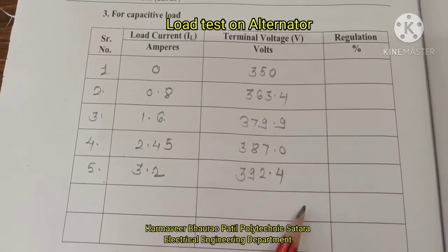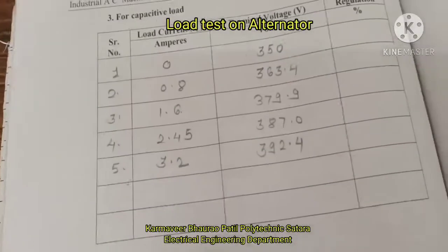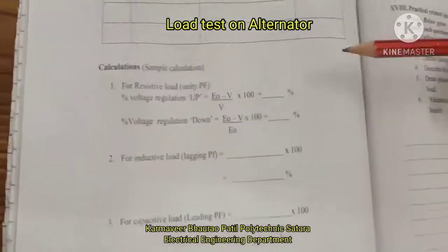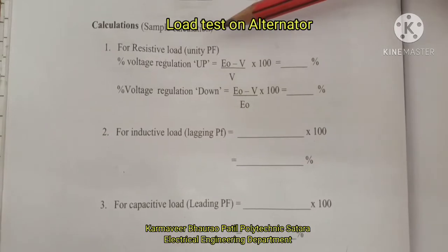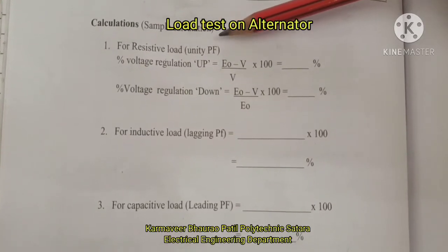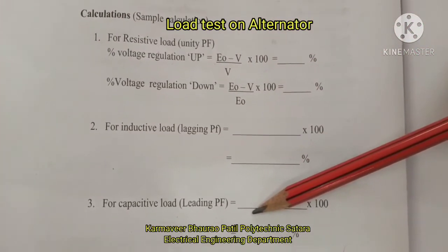So we have taken the readings for resistive and inductive load and capacitive load. Now calculate the regulation. It is a simple procedure, so I am not going to show the actual calculation, I will just explain. We have to do three different sample calculations: one for resistive load, then inductive load, and then capacitive load.